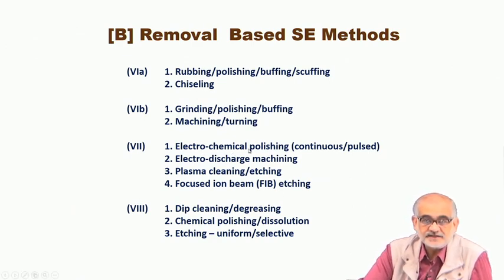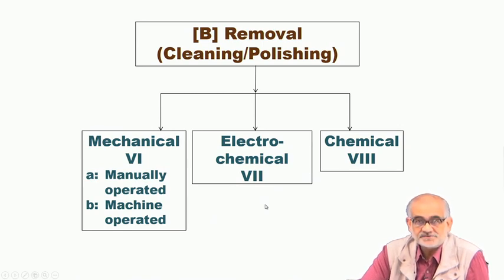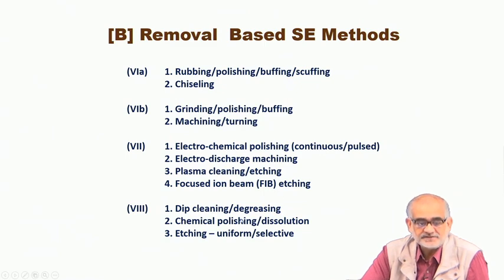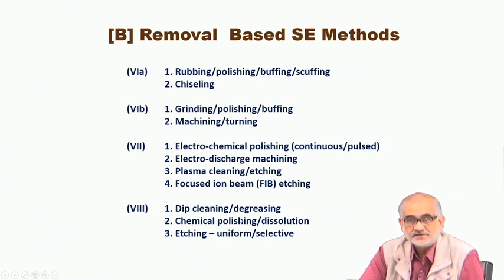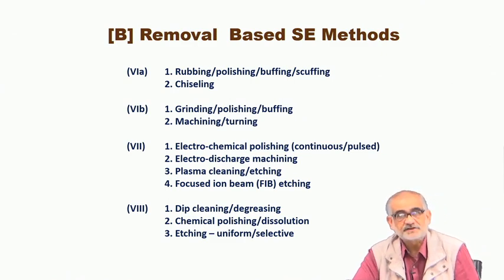But for typical industrial practices, we can also go into certain kinds of hot dipping processes. Say, for example, when we move into the chemical processes: in case of electrochemical processes, we need an electrolyte, we need two electrodes, the anode and cathode, and we expect ionic transport within the cell and electronic transport outside the cell. So, essentially we have a complete galvanic cell there. But in case of chemical methods, we do not necessarily employ transport involving movement of electrons and ions, but certainly there is dissolution by way of some chemical which employs controlled attack onto the surface.